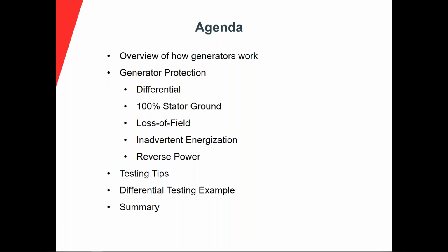We'll also go over generator protection: differentials, 100% stator ground, loss of field, inadvertent energization, and reverse power. For testing tips, at the end of the session we'll show a differential testing example and talk through that, and then we'll conclude with a summary.